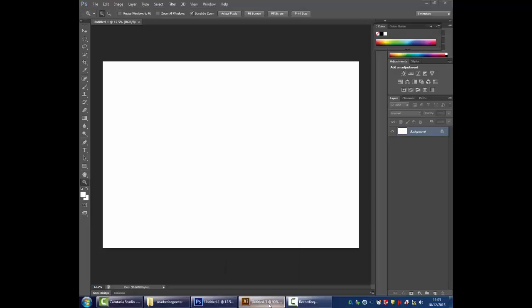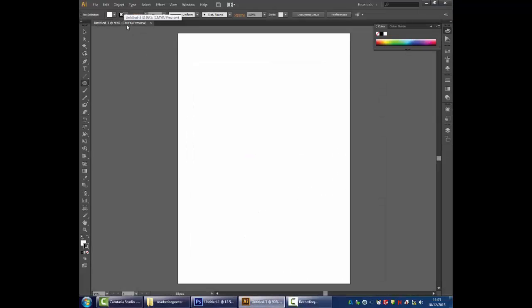In Illustrator, by default, it's cyan, magenta, yellow and black, and it's a replication of what it would look like from a printer, because printers don't print in red, green and blue, they print in cyan, magenta, yellow and black. If you want to look it up online, there's a whole load of science as to how those colours create black, theoretically, although we add black as well to make it jet black. But the screen works in red, green and blue, so if you work in cyan, magenta, yellow and black, it will just create the nearest equivalent of what it might look like on a printer, which means it's not quite as vivid in colours. So just be aware of that if you ever convert from one to the other.